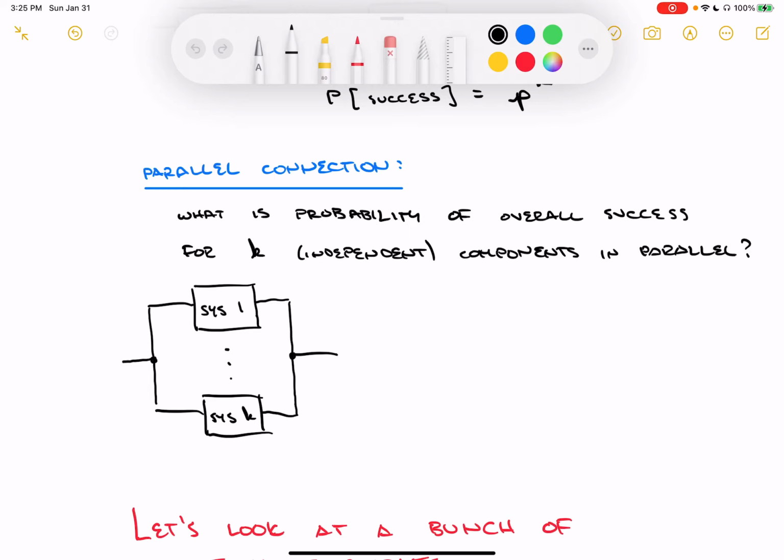This is a redundancy kind of approach to system engineering. So you might have heard cases of flight systems on an aircraft. There are critical systems on there where maybe they have 3 systems operating in parallel. So there's 3 redundant systems to do something like maybe flight speed or knowing the angle that the aircraft is banking. These different systems are done in a parallel kind of connection, right? They're done in a redundant way to help ensure better success probability overall.